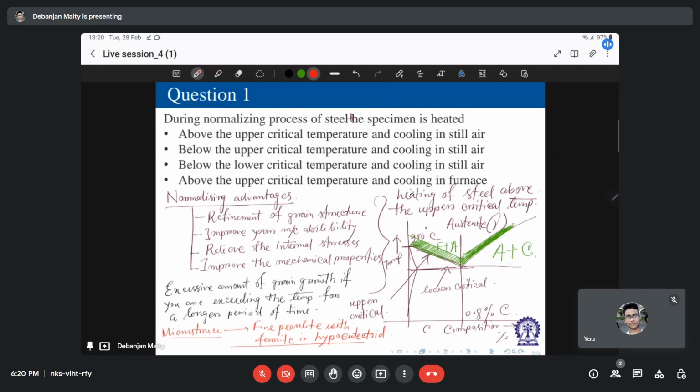Okay. I think up to this point, this should be understood, and it will be noticed that the newly formed grain boundaries do not correspond to the old ones basically. So if the initial structure is coarse-grained or irregular, normalizing leads to a considerable improvement of this structure together with improvement in mechanical properties, right?